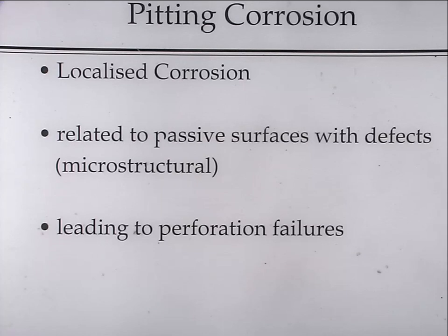This is the weld seam of the pipe. So this is a rolled and then seam welded pipe. And the pitting that is here is actually quite a reasonable distance away from the weld. The heat affected zone for the weld is probably a couple of centimetres maybe.